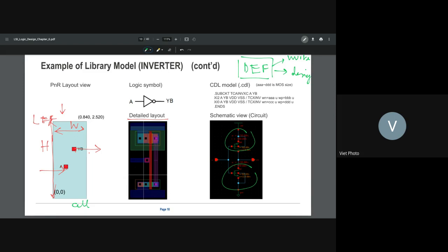So the routing rule can use the empty space here to insert the middle one into the cell. Usually the standard cell will be seen by the tool as open down to the middle one, so they can know, oh, I see there is nothing here, so they will route even the middle one through it.